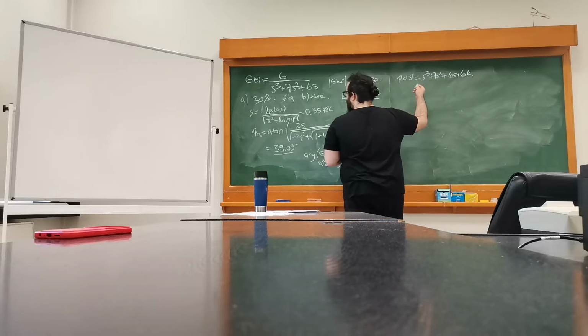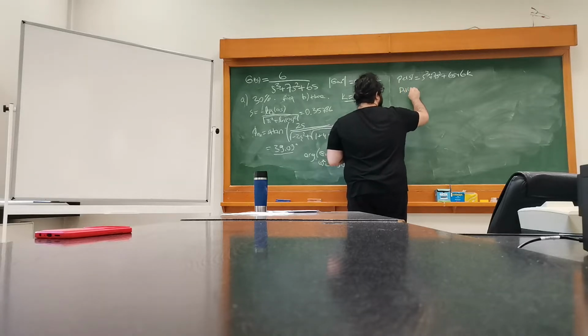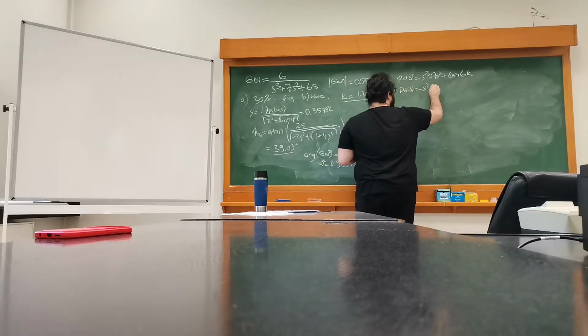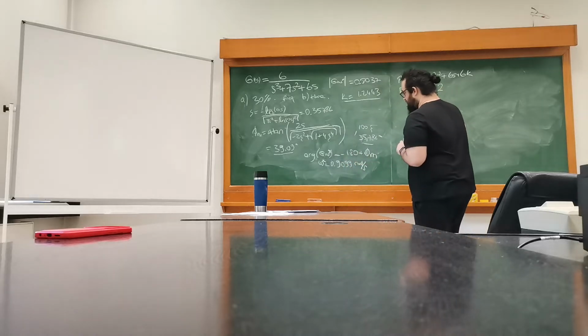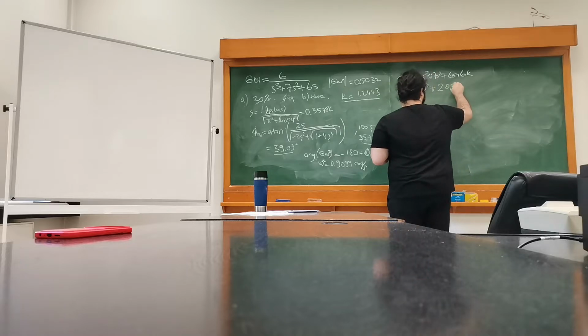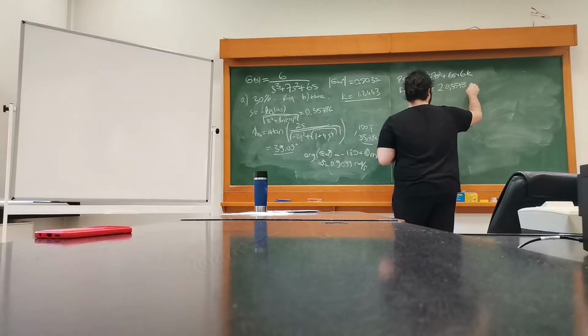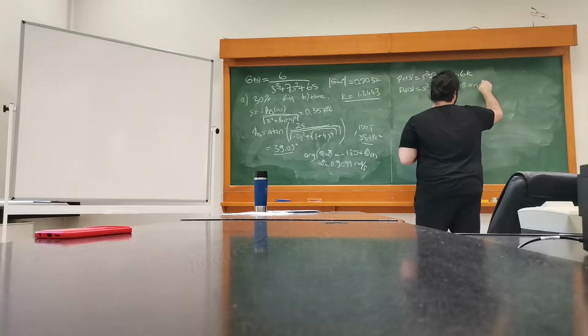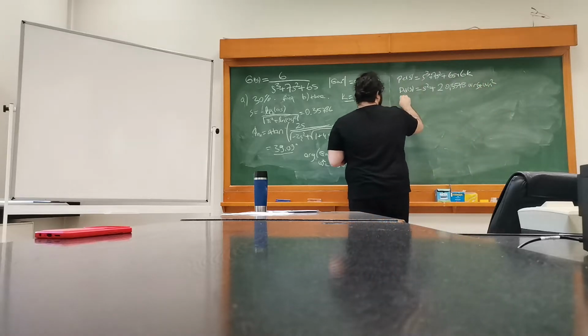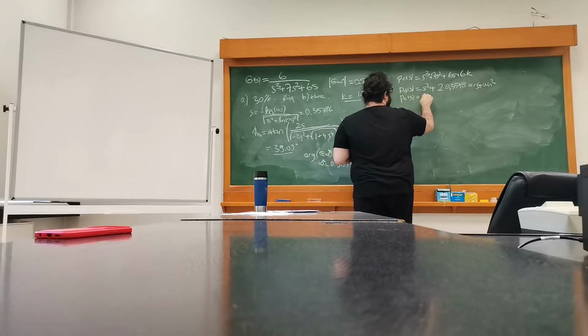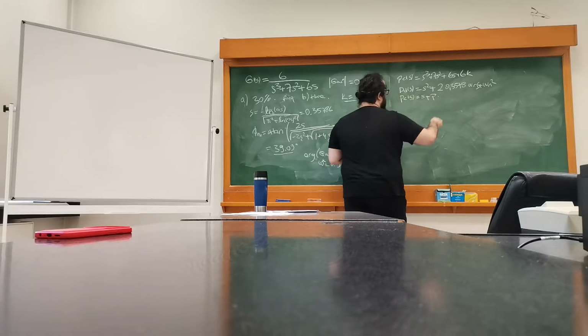Since we know what the zeta value is and we don't know what omega n is, our desired polynomial would be s squared plus 2 times zeta, which is 0.3578, omega n s plus omega n squared. And we need another pole, s plus p, since it's a third order system.